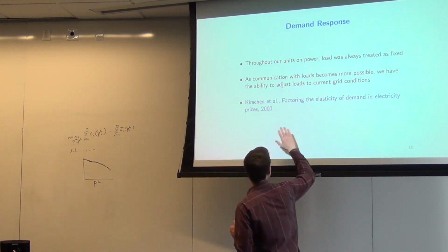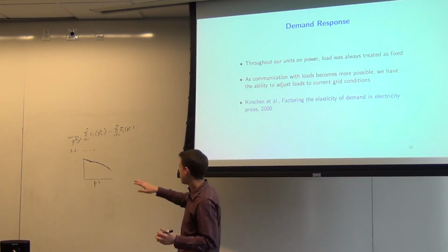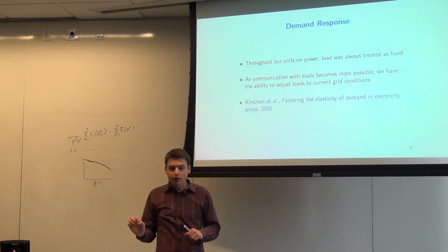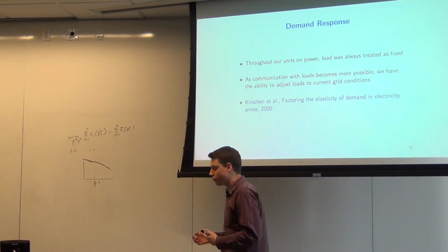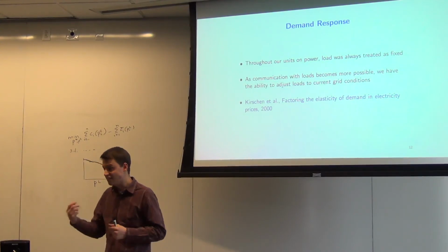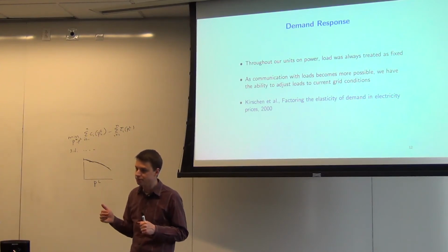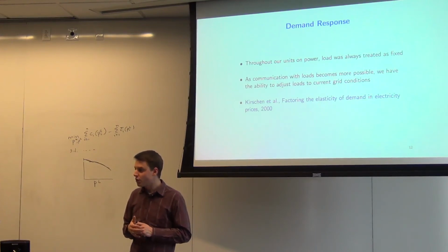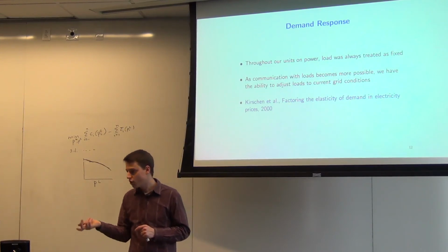You now have different prices at different nodes, because in computing the prices, you take into account the prices that you can gain or lose by increasing or decreasing load. And you just have much more flexibility in your problem. Using the example of renewables, where you've just lost a ton of power and can't get going fast enough again, you can accomplish the same thing by cutting the load a little bit, temporarily maybe, and then ramping it back up once your reserves can come by. So this ability, depending on its speed, can act very much like regulation or reserves.